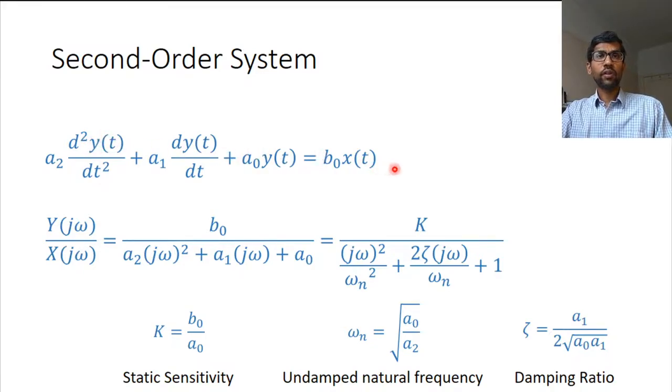Of course, my guess is that you have already done how to solve second order differential equations, and we will not go there, but let's look at some characteristics of such sensors. If you look at the frequency response and try to look at y over x, what you would find is you can get an equation like this, where there are some parameters that we have already looked at. In this case, we have three parameters that define a second order system.